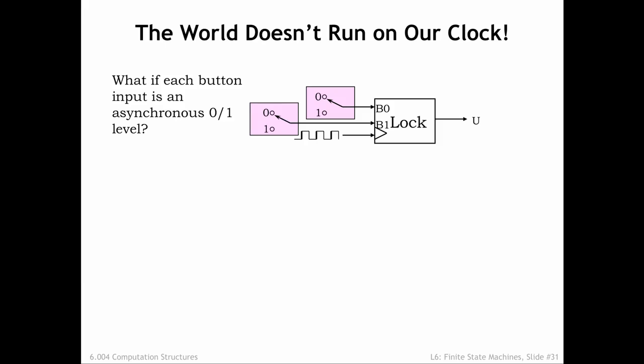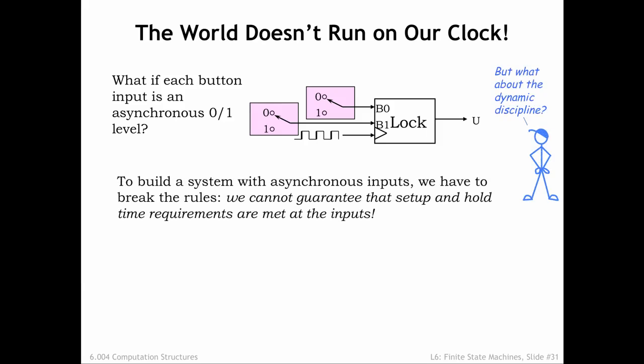This situation arises when the inputs arrive from the outside world, where the timing of events is not under our control. As we saw at the end of Chapter 5, to ensure reliable operation of the state registers, inputs to a sequential logic system have to obey setup and hold time constraints relative to the rising edge of the system clock.